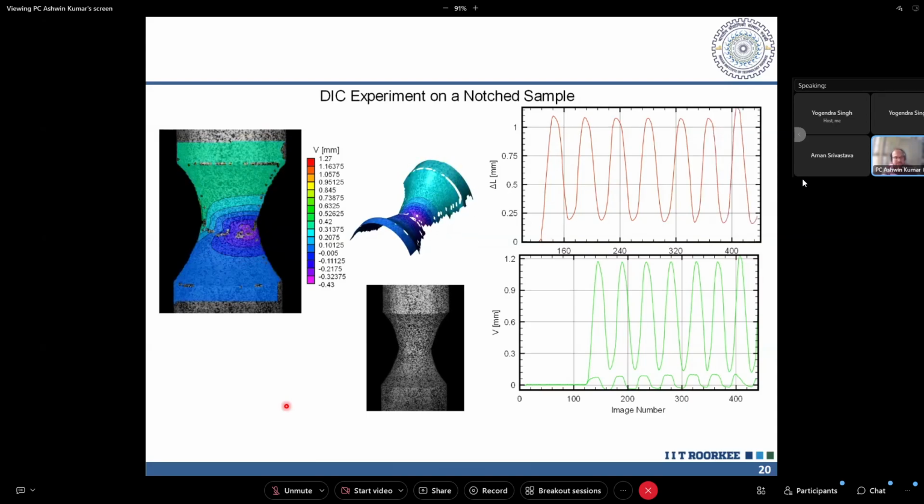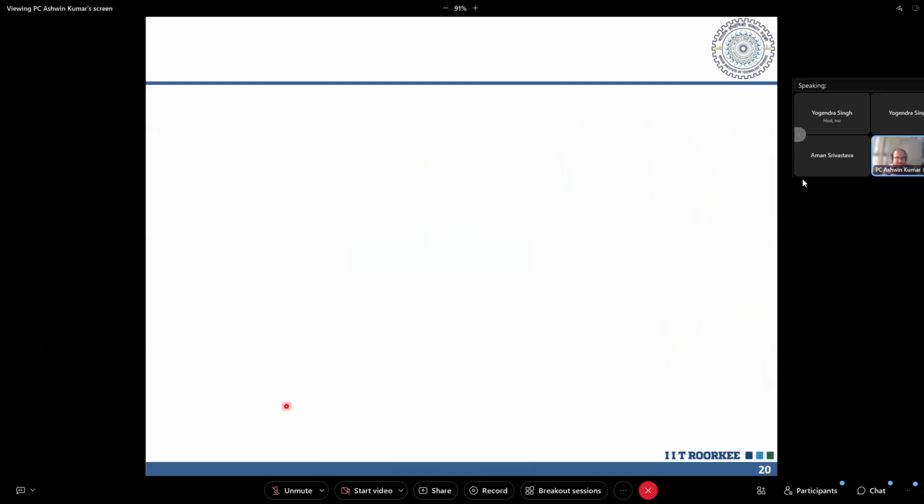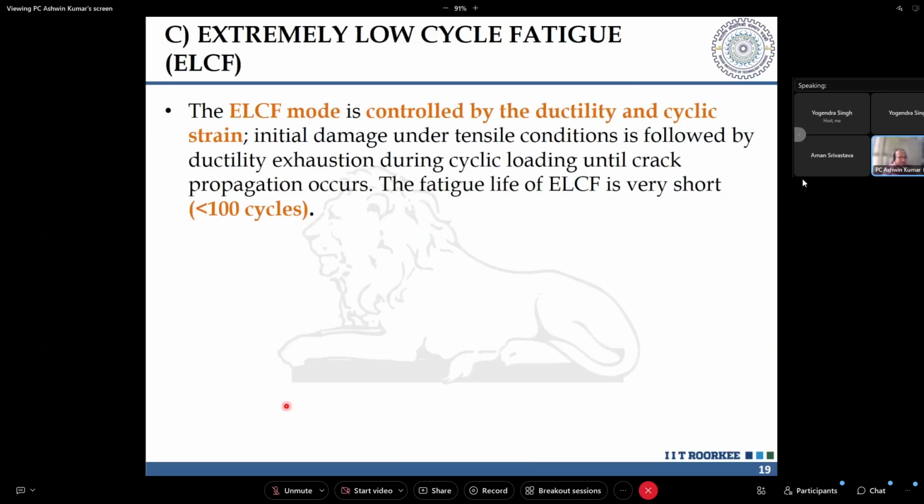In an earthquake, you understand that we are using a response reduction factor to reduce the earthquake forces imparted to the structure, because we want to depend upon the nonlinear deformation or ductility of the metal to dissipate the earthquake energy, right? So in those cases, in the 30-second earthquake that we talked about yesterday, the cyclic deformation might be 20 cycles, which might be more than enough to fracture that material.